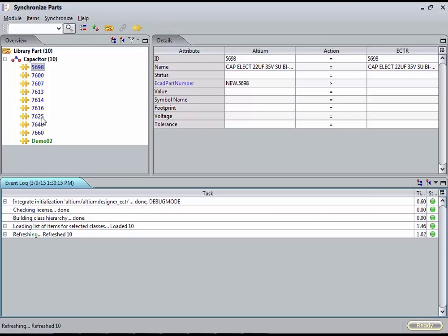The components shown here are marked with different colors. The blue color is indicating that the parameter information in the development library is different to the one in the PLM system. Green marked components are not existing in the PLM system yet. Therefore, the column of the PLM system is empty. Black marked components are already synchronized. In difference to that, red marked components are not existing at all in the development library yet.